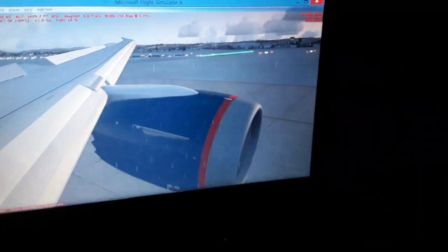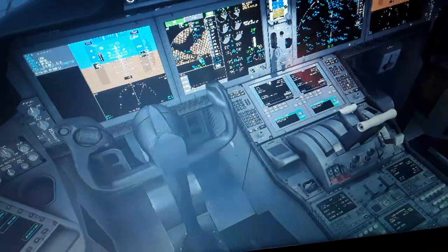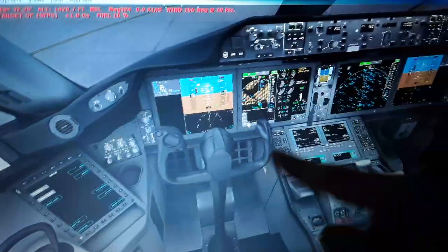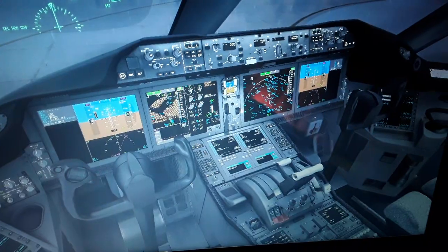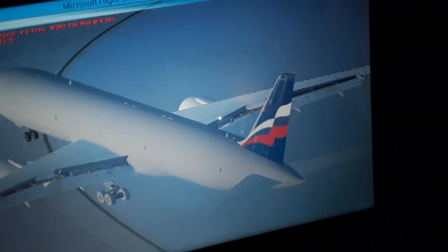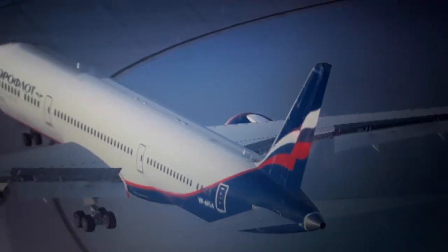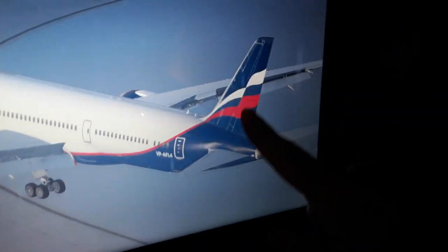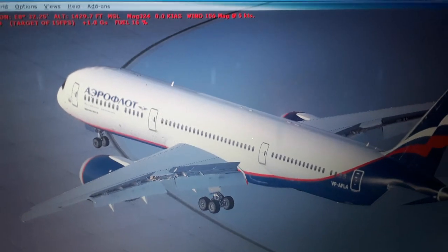So we use the rudder pedals here for the rudder. You can see, make left and right turns using the rudder pedals. We have also the toe brakes in the rudder pedals and the nose wheel steering. We control the tiller. It's interconnected, like so like that. So the left and right rudder pedal is the rudder here, right or left, like this, as you can see. Also, on the ground, the rudder becomes aerodynamically effective at 45 knots or 70 kilometers an hour in takeoff.